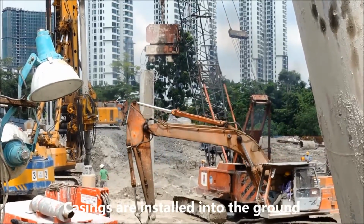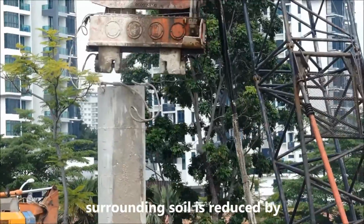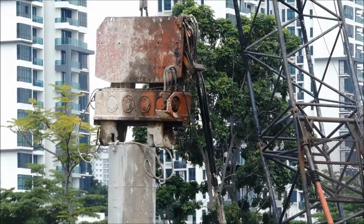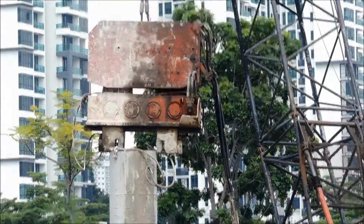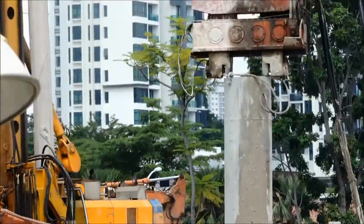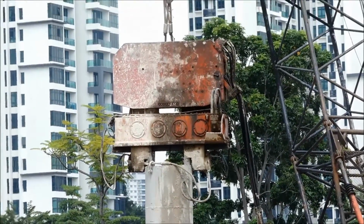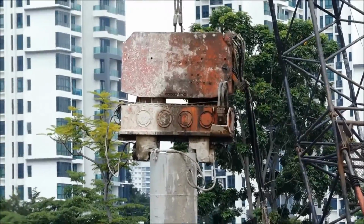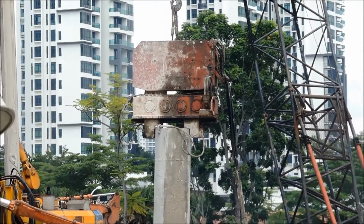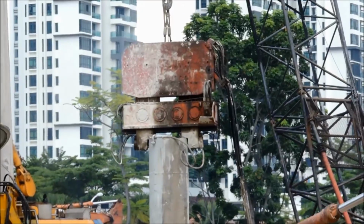Casings are installed into the ground using externally induced vibration. Friction between casing and surrounding soil is reduced by vibration generated from an attached vibro hammer. The casing penetrates the ground due to this vibration.